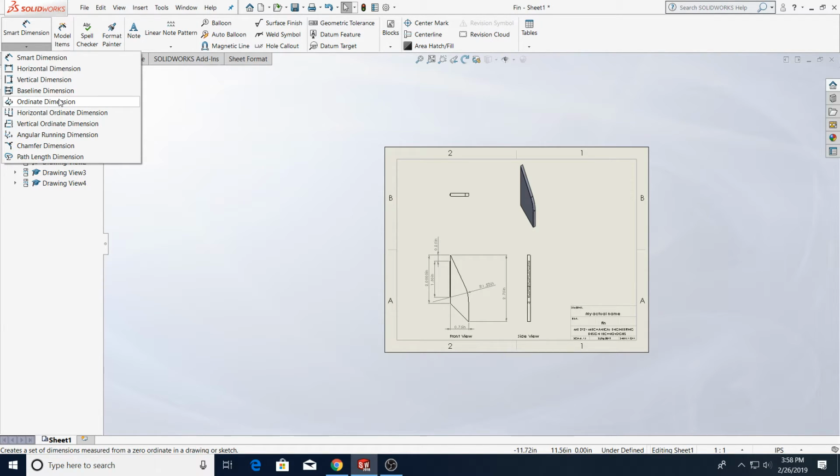If you have a repeated dimension and you're referencing a single data point, once you get past 3 or 4 dimensions shown, it gets a little bit too complex to keep track of easily, and you can busy up your dimensions. Instead it might make more sense to use a style of dimensioning called ordinal or ordinate dimensioning.